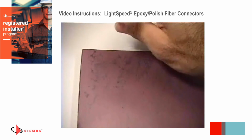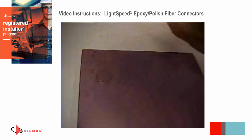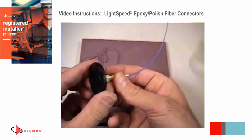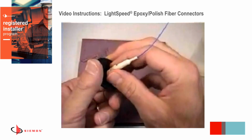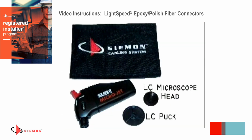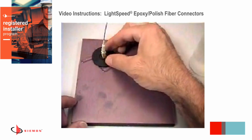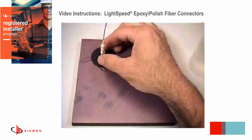Add a minimum of 3 or 4 drops of distilled deionized water onto the section of film to be used. Carefully insert the connector ferrule into the appropriate polishing puck and gently place onto the pad. For LC connectors, use the puck provided with the LC upgrade kit. Avoid bumping the unpolished ferrule tip on the puck or crushing the tip down onto the pad.